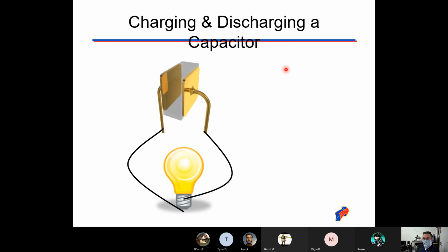One of the things you have to be real careful about with capacitors is that they will hold a charge for a very long time. So if you find an old TV, don't touch it, or an old refrigerator, things like that, they have these massive capacitors in them. And people die because they go mess with these tube TVs that have this humongous capacitor. And what I mean by humongous, it's like 4 or 5 inches round, and it sits on the back of these TVs.